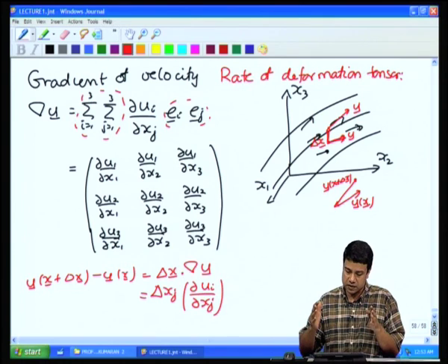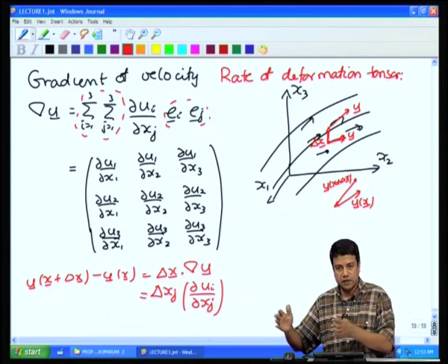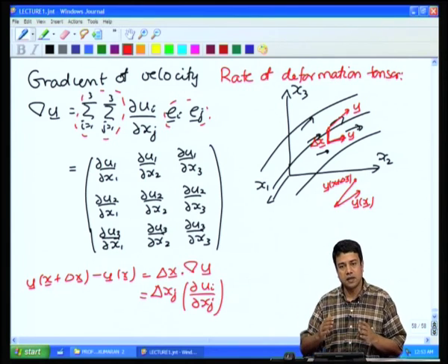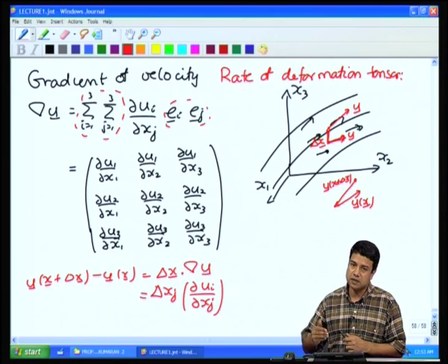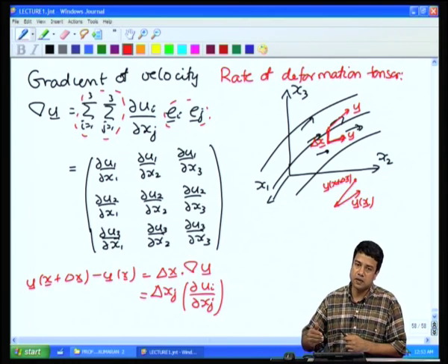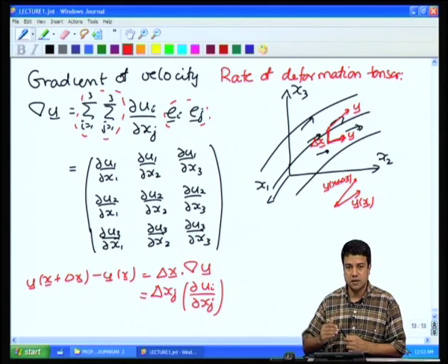If I have stresses in a certain fixed reference frame, and I take that same experiment and move the reference frame with a constant velocity, I cannot generate stresses within the system. If the gradient of the velocity is equal to 0, that means that the velocity does not vary as I go from point to point within the system. Velocity is a constant, there cannot be stresses.